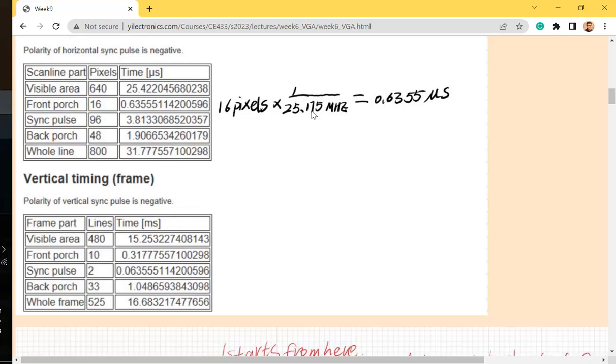So your role here is to program your Verilog to match whatever is showing in the table and to make it work. You are computer engineers, not embedded or C++ software developers right now. You are working at the very bottom level, down to the timing level. You have to care about the timing diagram instead of just getting the libraries from Arduino and programming it. That's very high level, but now it's very bottom.